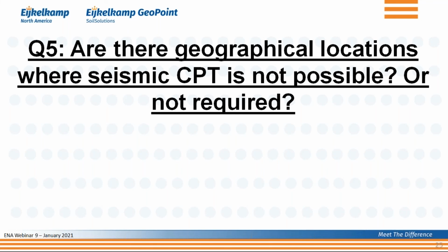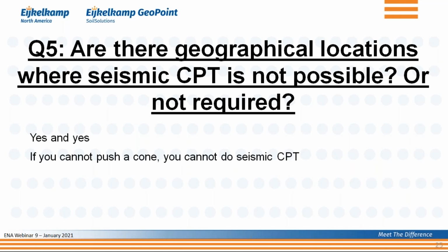Now that we know where we can apply SCPT, is there anywhere where it is not recommended to conduct seismic CPT, or is it not possible in certain geographical locations? Well, again, a relatively simple question. Are there locations where CPT is not possible? Absolutely. Are there places where it's not required? Yep. If you cannot push a cone, you cannot do seismic CPT.